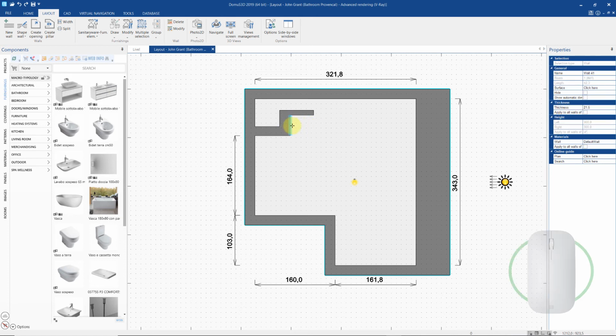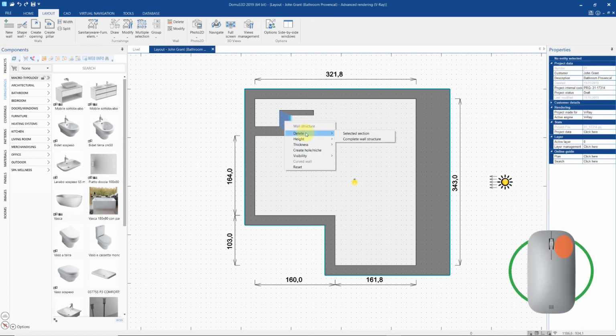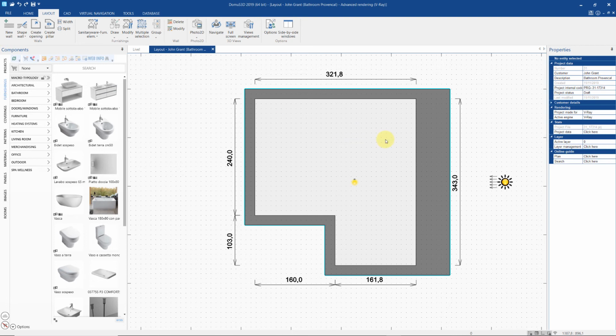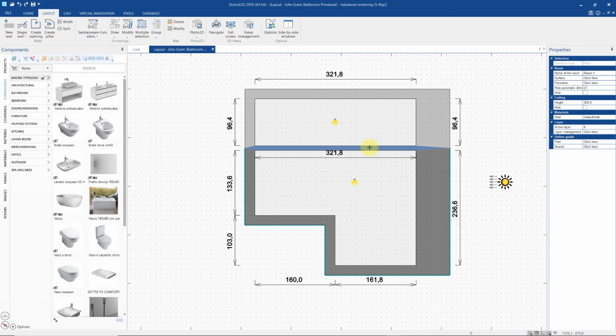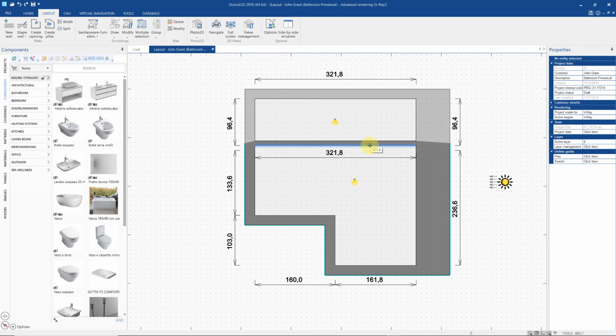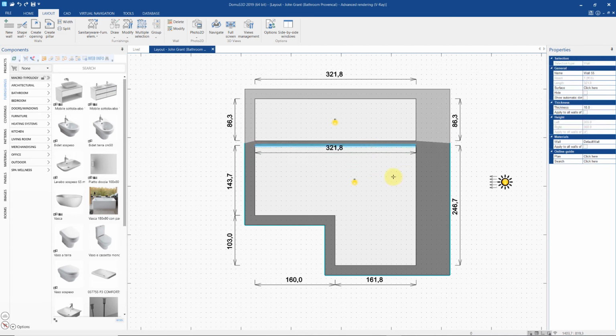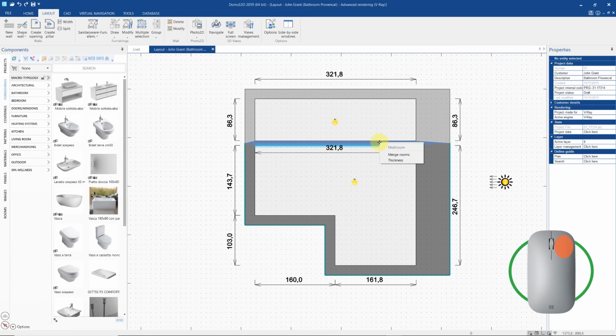To delete a wall, we can right-click and select Delete, and then choose whether we want to delete only the highlighted segment that I clicked on, or all the interior walls connected to one another. When the interior walls are drawn to close off a part of the room, the original room will be automatically divided into two separate rooms. We can right-click on the wall again and choose whether to delete the room or restore our single room.